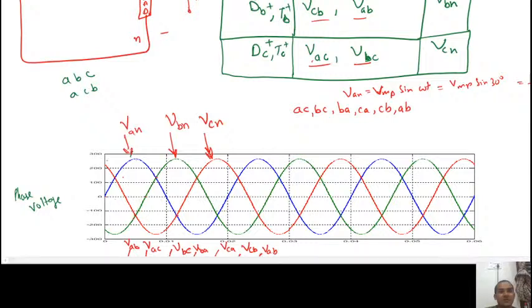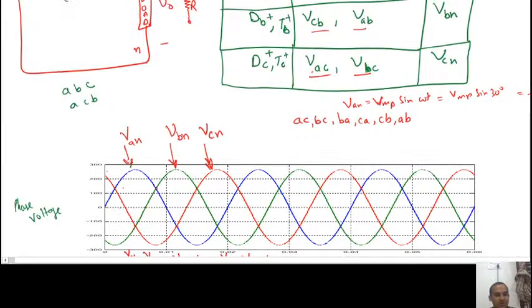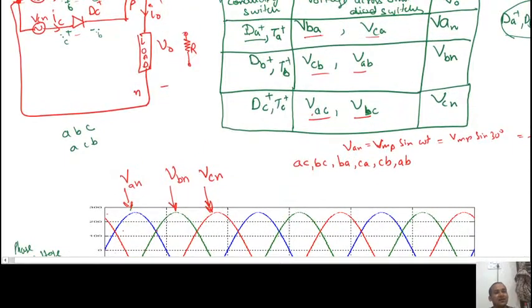So if you see, say that the starting voltage or load voltage was 0, what will happen from 0 to 30? If the current is not flowing in the load, the phase voltage will decide. Please catch these concepts very clearly. Only if and only if current is flowing in the load, then only the switches will experience line voltage across them.